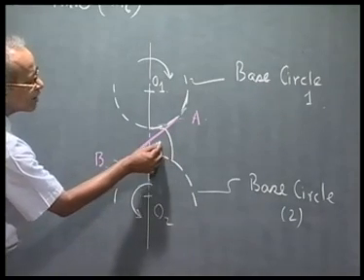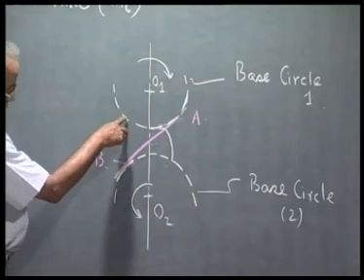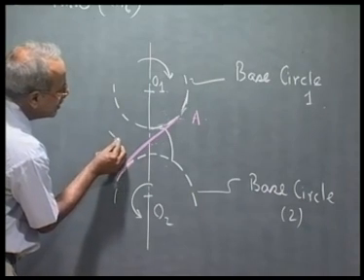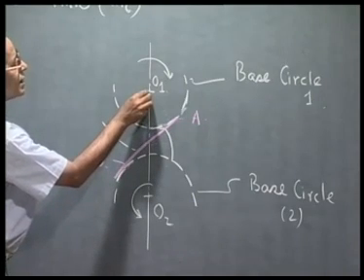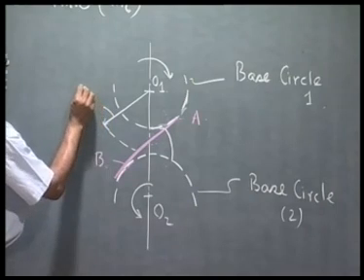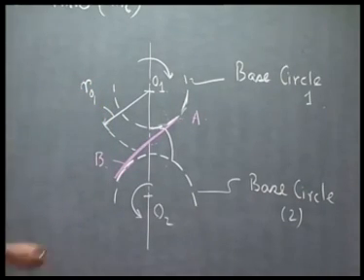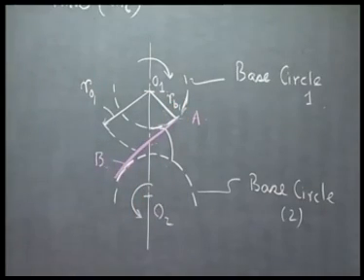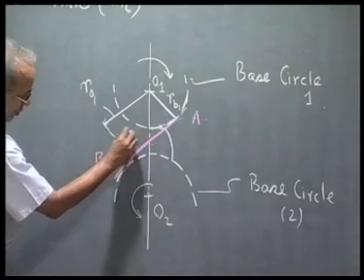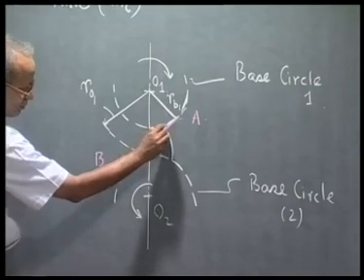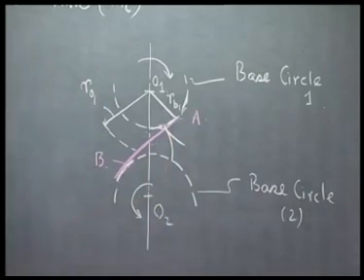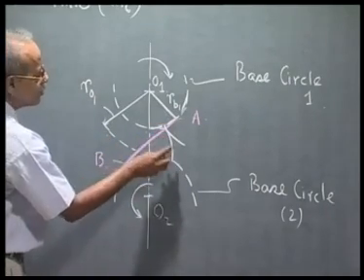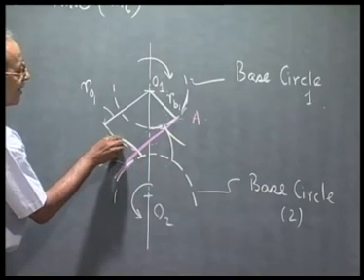Now, this gear starts rotating this way. How long will this tooth remain in contact with the tooth on the other gear, gear number 1? So long as the outer circle of this gear is in contact. So, this is the addendum circle of the gear 1. Let me call it radius RO1, that is the outer radius of gear 1, and this is RB1. So, as this tooth rotates, this tooth comes here, and when this outer circle leaves this line, the contact is lost with this particular gear. So, if I draw this tooth here, this is where the contact